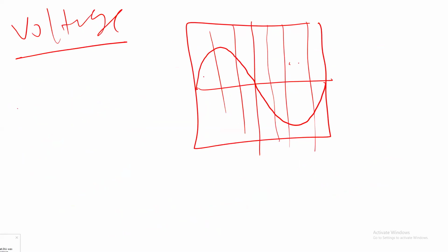But in the case of an AC signal, the oscilloscope is going to be very useful, because you are going to display the signal. After you display a signal, you can measure the time, or you can count how many squares there are to measure the voltage.